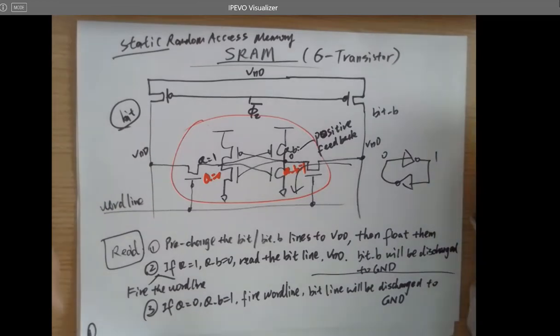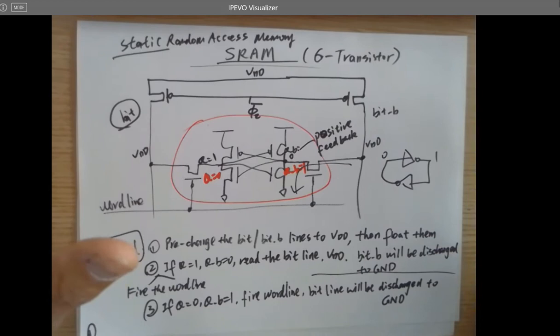And for the DRAM, you can buy a DRAM card from the market, right? It's just the cost right now is super low. Only like $60, you can buy a 64 gigabytes card or something. The reason for that is they can integrate more DRAM cells into a smaller size with a lower cost. And so they want to integrate as many memory cells as possible for the DRAM. So they want to use smaller capacitors. And when the capacitors are smaller, the impact from the metal lines will be bigger. So that's the kind of trade-off of the circuit design.